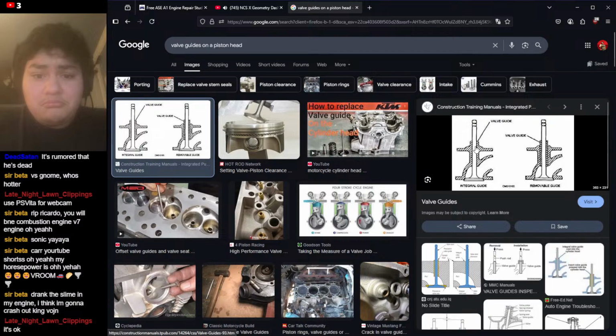So, oil is being run through here to lubricate the in and out of the valve. You don't really want oil down here, because if the valve opens and there's oil here, it can get inside your cylinder, and if you burn oil, your exhaust will come out very light blue. So if you have consistent light blue smoke, that's bad.